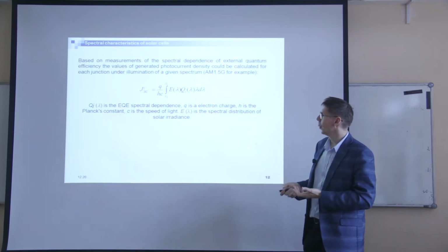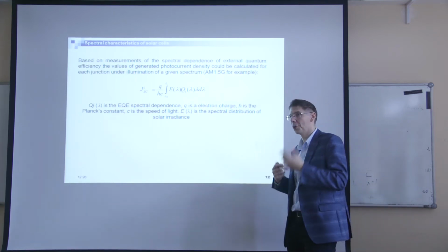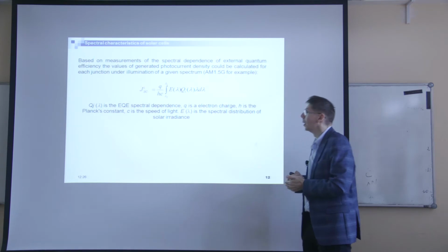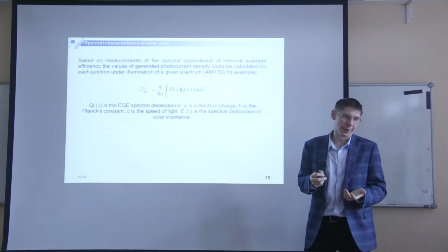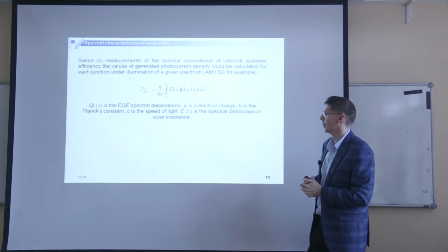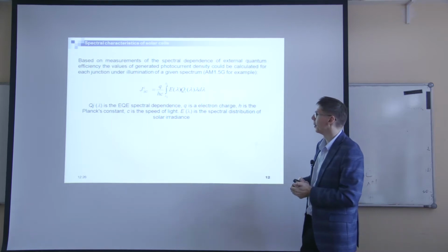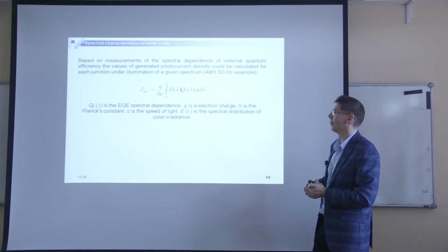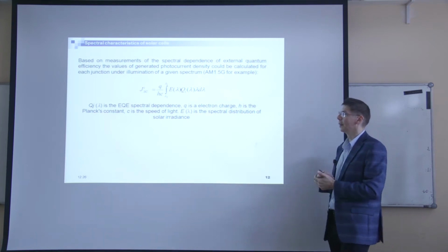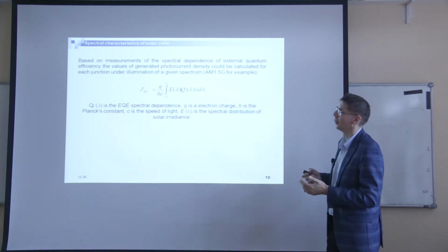And then when you have calculated this value, you can really estimate the short circuit current of the multi-junction solar cell, and you can calculate the parameters which are required for better IV curve measurements, like the spectral mismatch coefficient M, and any other coefficients to get ideas about what kind of reference solar cell to use and what kind of solar simulator to use.